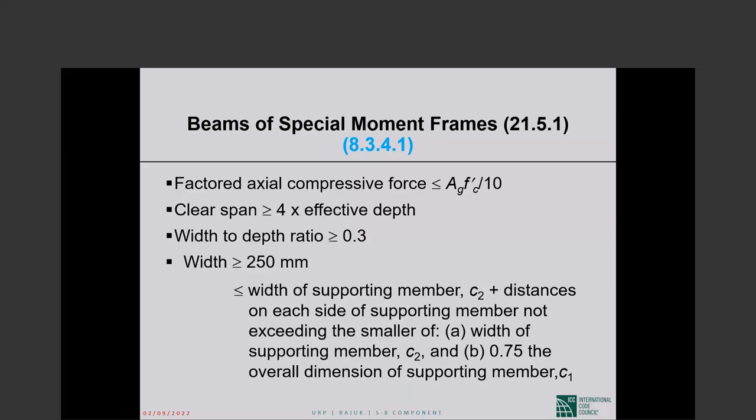You probably have the slab and no beam sticking out. So in that case, the slenderness may not be a problem. So if you don't count on those missing beams as part of your seismic force resisting system, you should be okay. This is a general answer without looking at exactly what you have in mind.